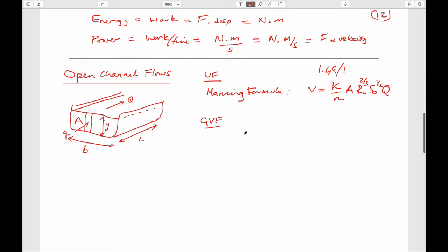And so for gradually varying flows, we can define the energy of the system as being equal to the depth plus flow per unit width squared divided by 2 times gravity times the depth squared. All in units of length, and so this energy is in units of length in this particular case as well, so I guess it's force per unit volume is really what it ends up being an evaluation of.